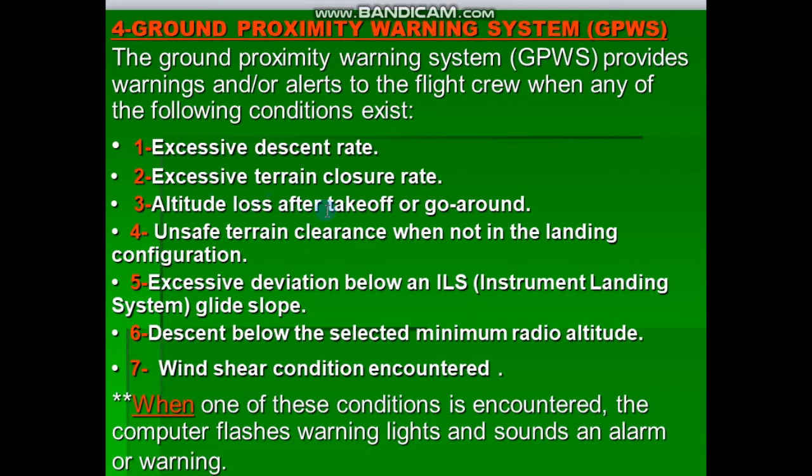After that, descent below the selected minimum radio altitude. And the last one, wind shear condition encountered. When one of these conditions is encountered, the computer flashes warning lights and sounds an alarm or warning.